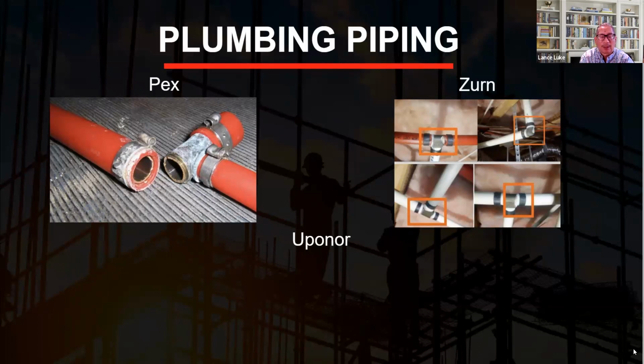What happened was, in the beginning, it was determined that the hot water side, because of the temperature, caused the metal connector to prematurely deteriorate and corrode. And through testing, it was found that the metal had the wrong percentages of zinc and brass. And believe it or not, there's actually a code requirement that dictates the percentage of each type. And it was proven to be wrong in the manufacturing, and that's what caused the premature failure, mainly on the hot water side.